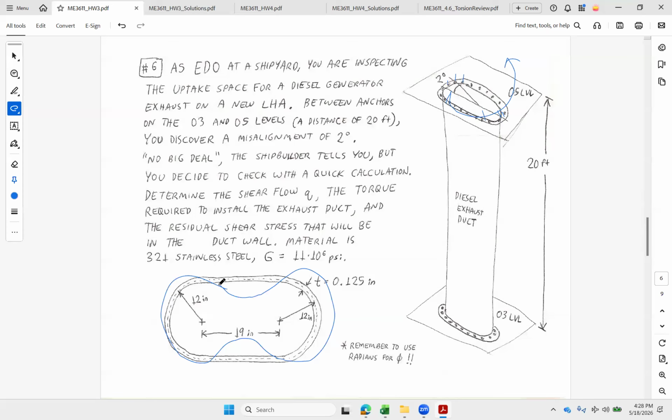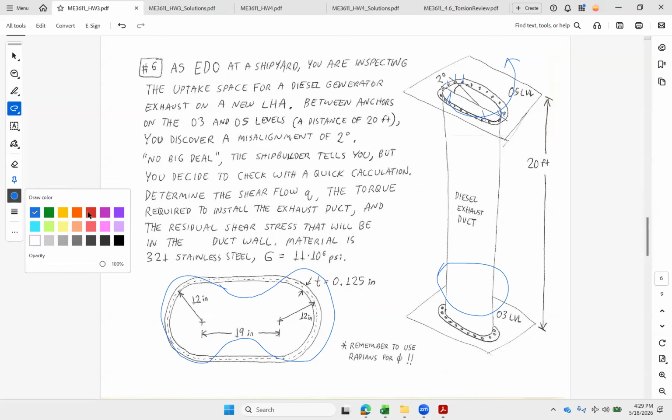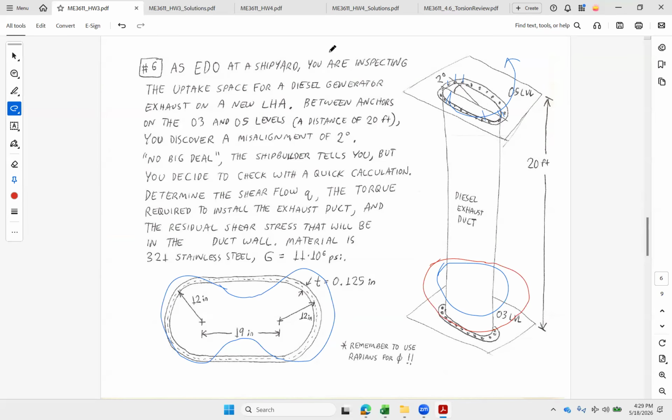You probably have seen these in gas turbine exhaust, but that's okay because the flow's pretty constant. So it changes shape and stays that way. But in a diesel, it's exhaust pulse every time the cylinder fires, right? So it's kind of reciprocating, goes back and forth like that. Whereas in a round duct, I'm starting with this shape, and my deformed shape is just going to be, still round. There's no concentrations to it.